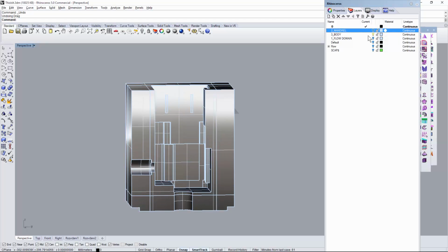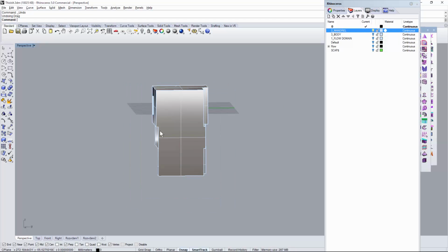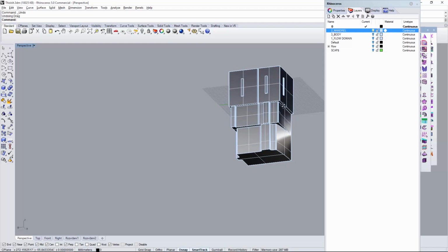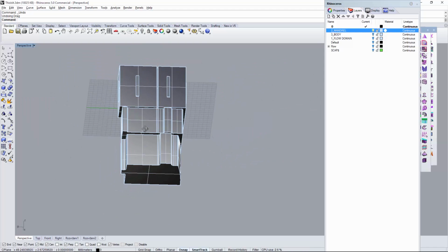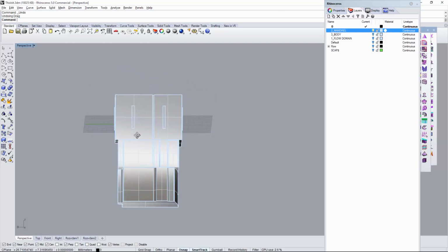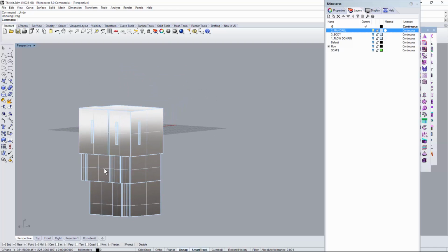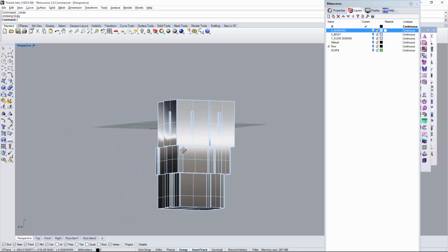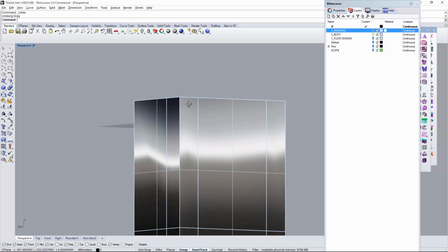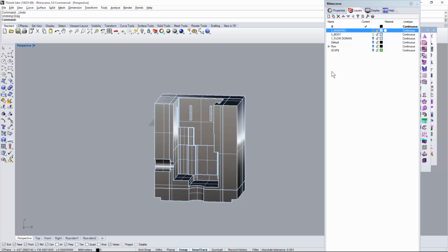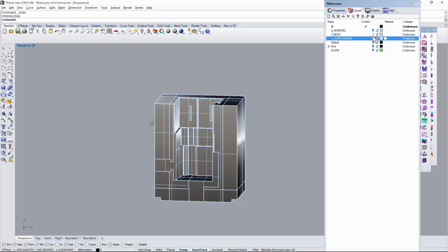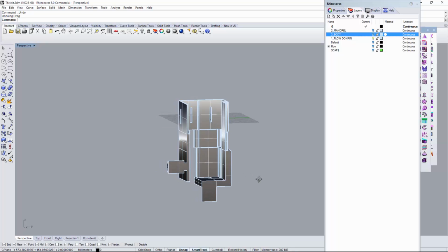Now, of course, the mandrel does not look as it is displayed here, because this looks like one big block, but that's never made that way, because they really have 3 plates here, and the mandrel really consists of plates. Each plate needs to be hauled through these mandrel supports to the outer body, and that's why we see on the outer body also the mandrel supports. The body and the mandrel create in between the flow domain. So, this is the flow domain we'll be looking at.